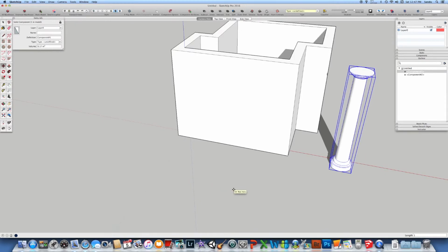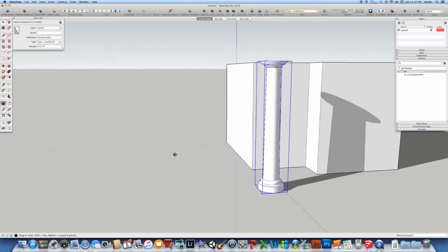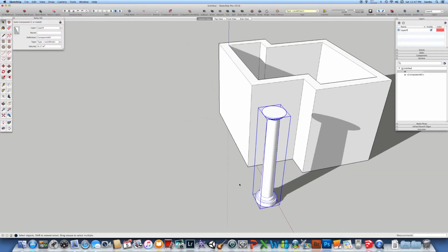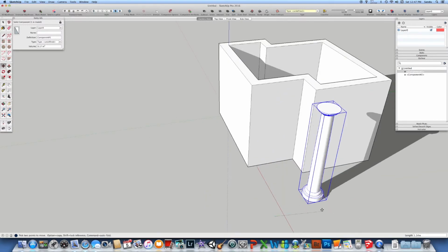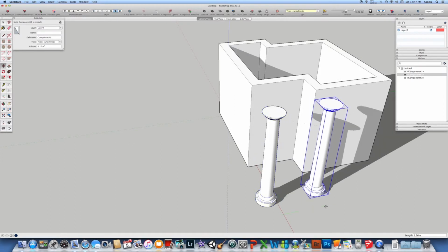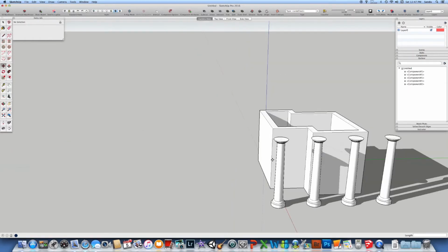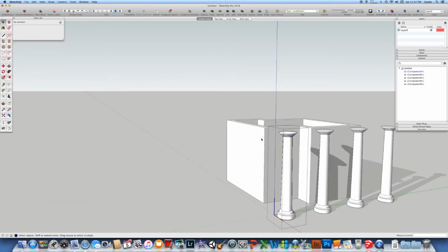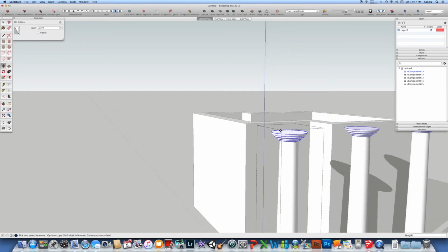1 meter. And if I want to have this column at the same height as the other one, and let's say we move this column to the side with a copy, and we create let's say 3 copies, so you click X3, and if I want all of those to be the same height as the wall, I can just select the component first, double click on it, and I can just move those up and down to whatever dimension you like to have.